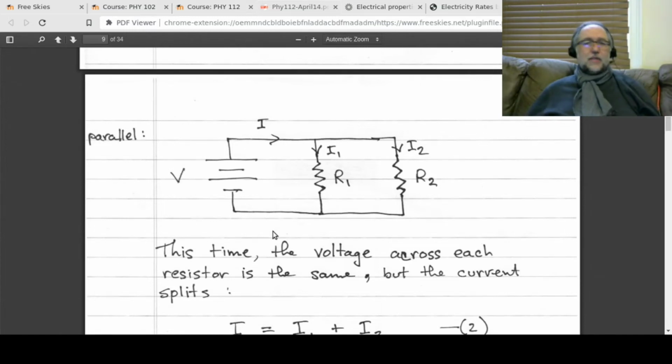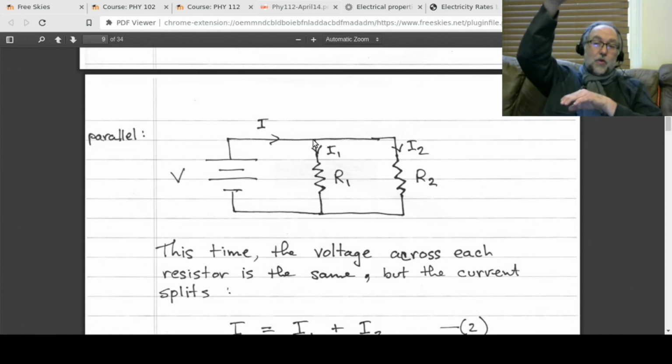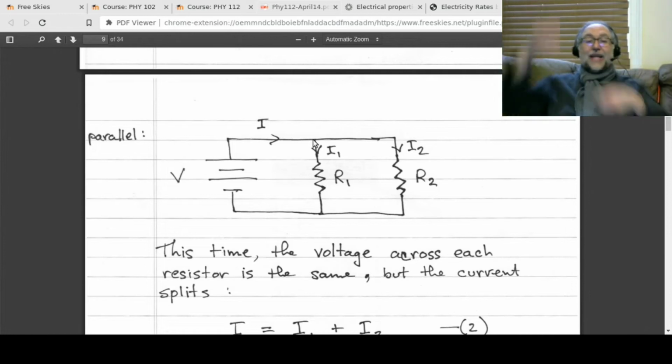So let's just pick a number, 10 volts. Suppose up here you're at 10 volts. This is the 10 volt side of the battery. It's 10 volts all along the wire until you get to that junction. It's not like a current, it's an energy. It's like that analogy I gave you in the last video, where you're so high above the ground, making the analogy with gravity. You're at 10 volts height all the way through here. So both of these resistors start off at 10 volts.